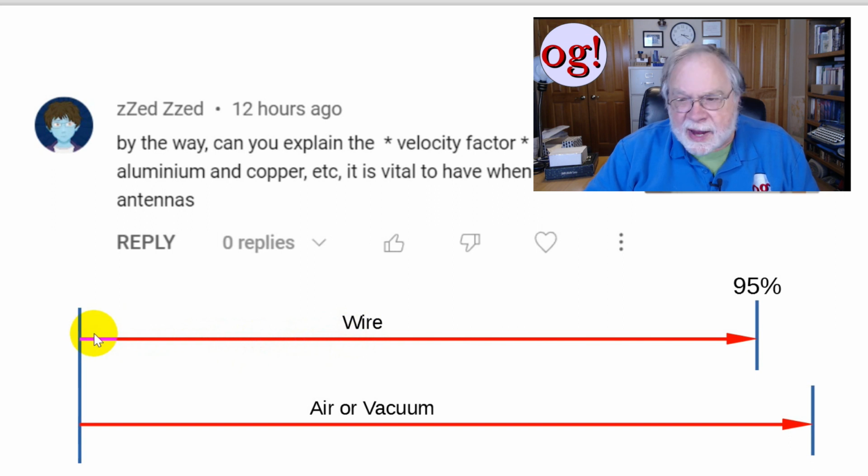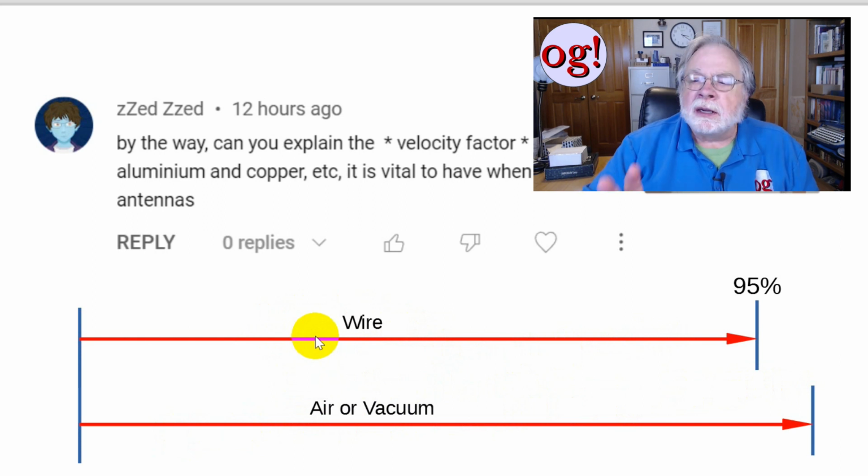Remember that when we get outside of the radio itself, we are no longer using circuit theory to figure out what's going on, because it gives us an incomplete explanation. We use electromagnetic field theory, but we can cut that down to a few things that are of use to us as hams. And one of them is the velocity factor. It just helps cut things to the right length. Okay?